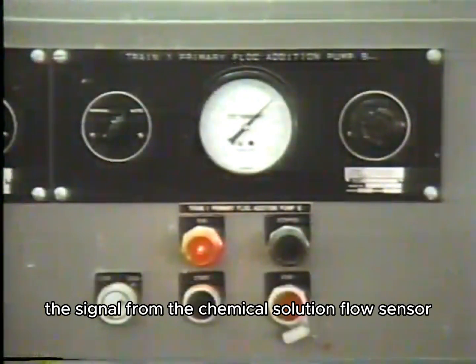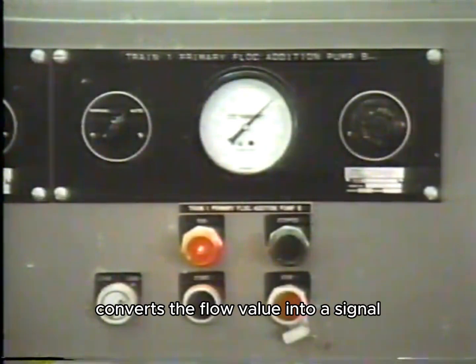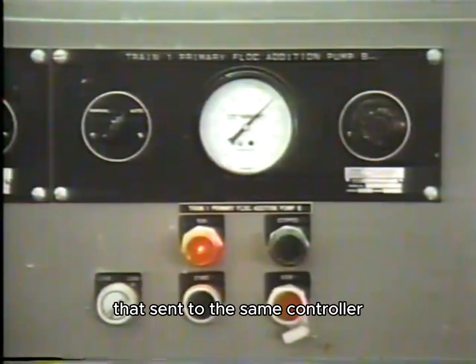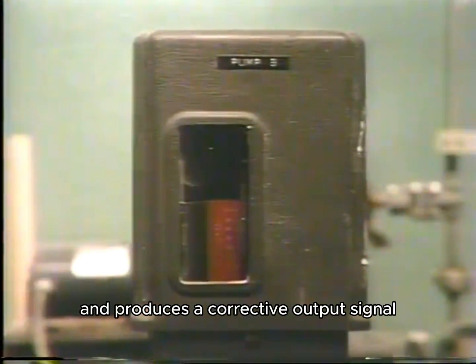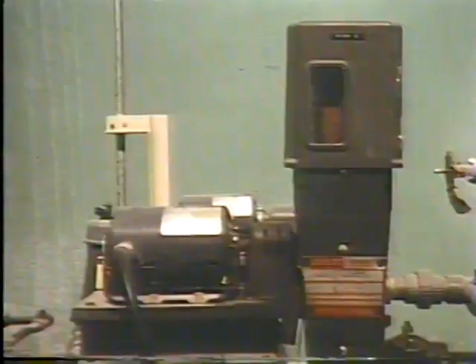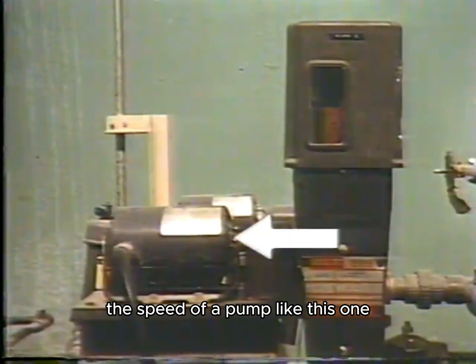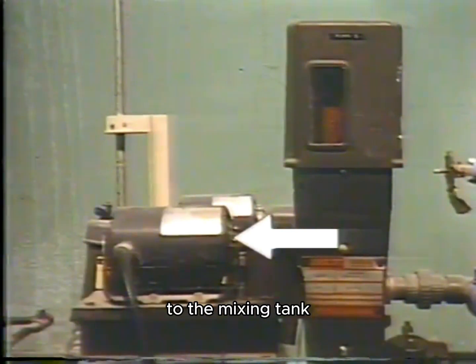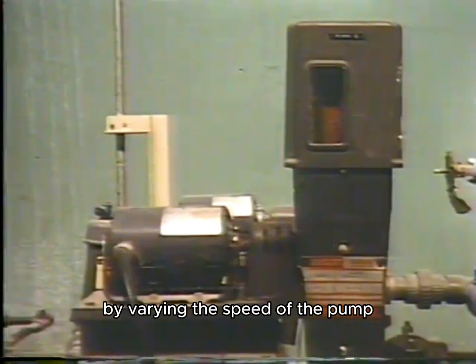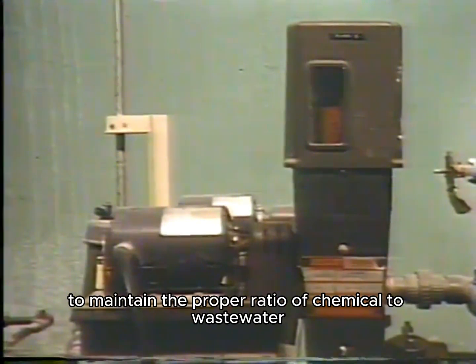The signal from the chemical solution flow sensor goes to a transmitter like this one. This transmitter also converts the flow value into a signal that's sent to the same controller. The controller processes this input, compares it to set point, and produces a corrective output signal. The output from the controller is used to vary the speed of a pump like this one. This pump manipulates the flow of chemical solution to the mixing tank. By varying the speed of the pump, chemical flow can be increased or decreased to maintain the proper ratio of chemical to wastewater.